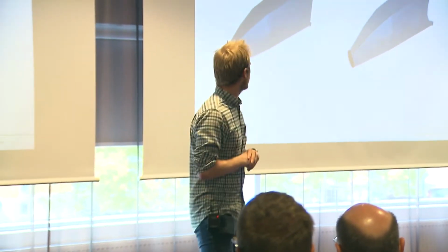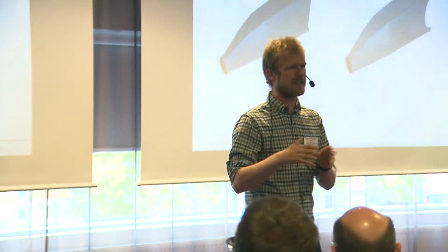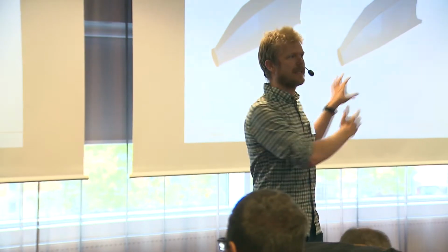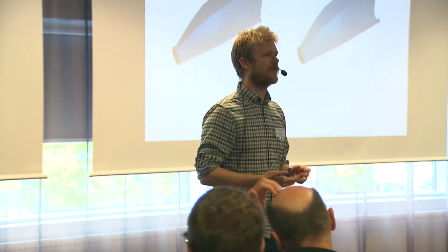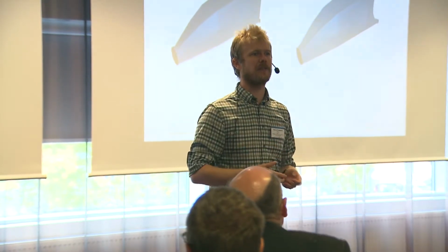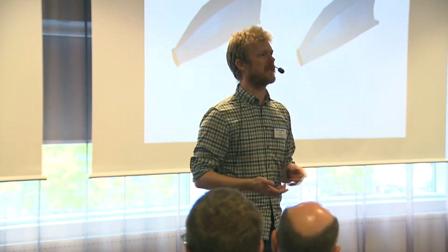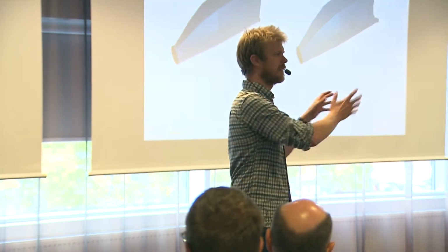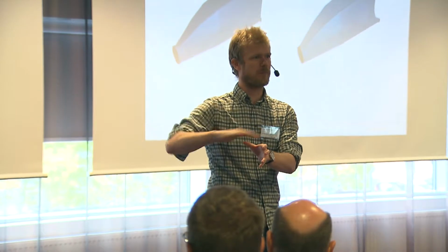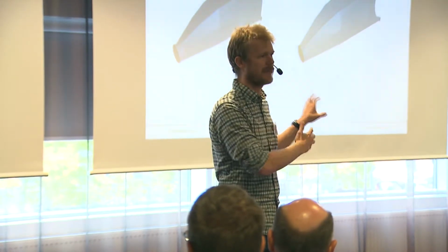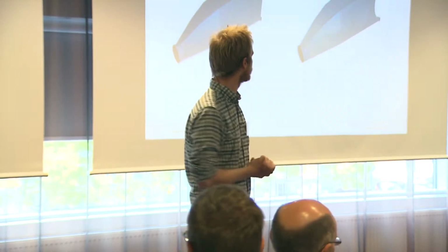So what we typically do is, this is not even going on in the CAD program, even though it's changing at the moment, but adding lattice structures to parts has been something you do in your additive manufacturing slicing and hatching software like Netfabb and Magics. So it's not even sitting at the design engineer's desk, it's at the manufacturing side of things where you prepare your build files, then you add some lattice as an afterthought.